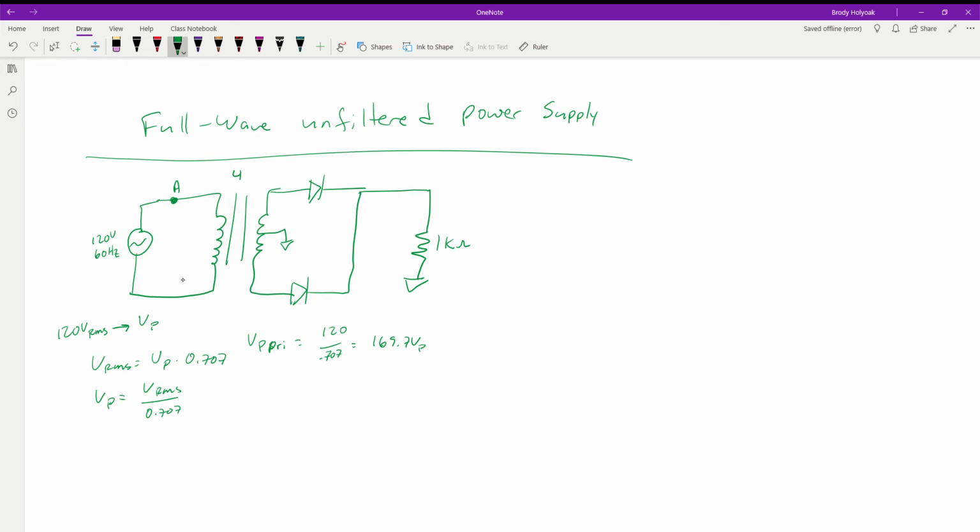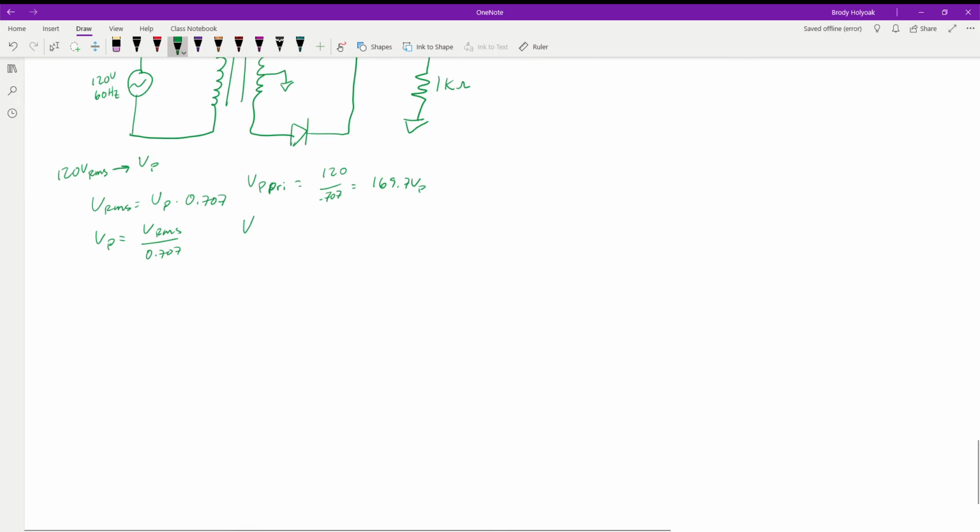Now we go through our transformer, and in my case I'm using a 4-to-1. Remember, when you're doing the calculations, go through with the value that you've calculated for your turns ratio. You already have the voltage that things step down to, so just follow that ratio again. For V secondary, I'm going to swap this designation around a little bit, so it's V primary in voltage peak.